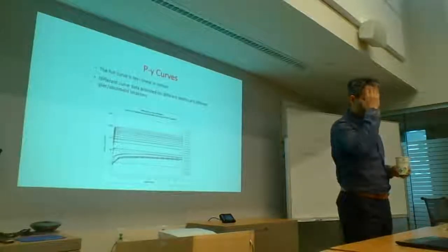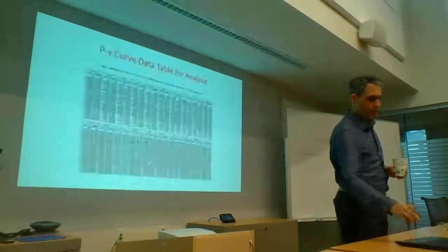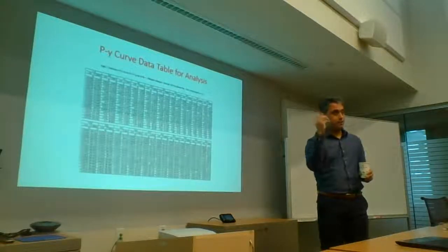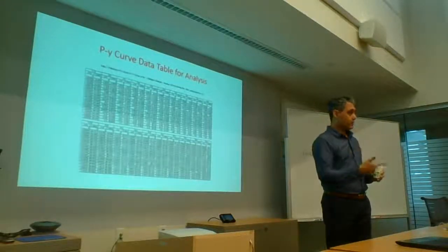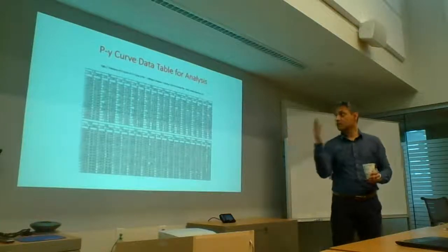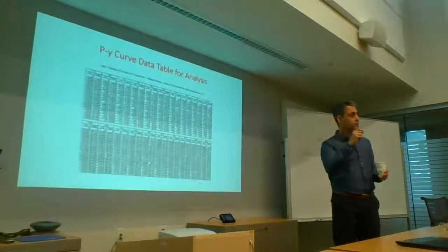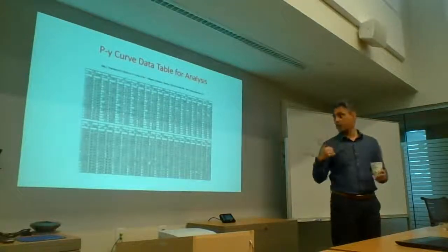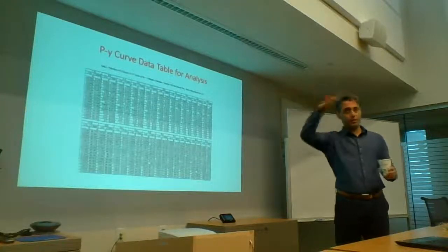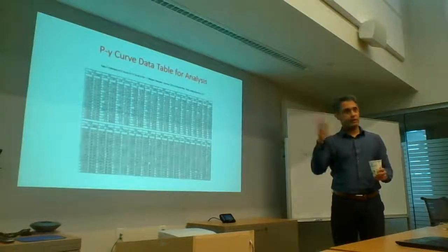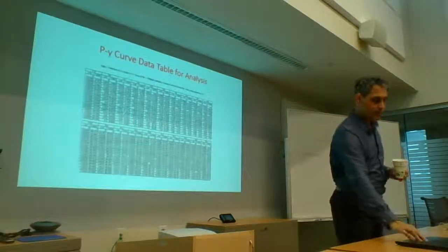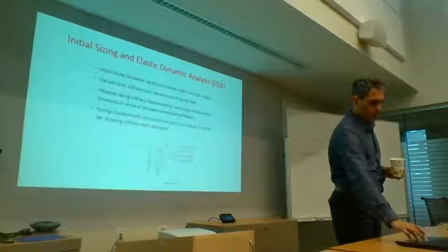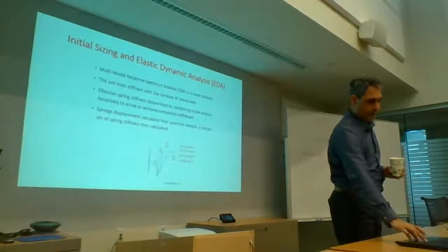So when you're doing a response spectrum analysis, you cannot put these values in there. You have to just give it a stiffness. And that becomes a bit of an automation exercise, because for each spring you've got to converge it. You pick one stiffness, you get the force in it, and you figure out if the force is above the plateau line, then you have to go and correct it. So you have to do a few iterations. You've got to set up some spreadsheets. We've seen that, and that's what I was talking about.